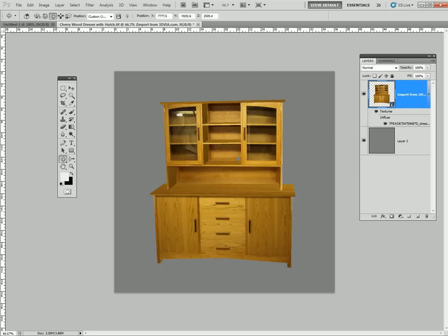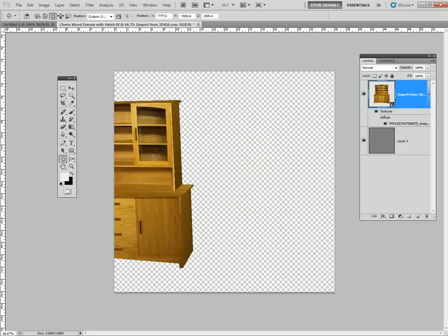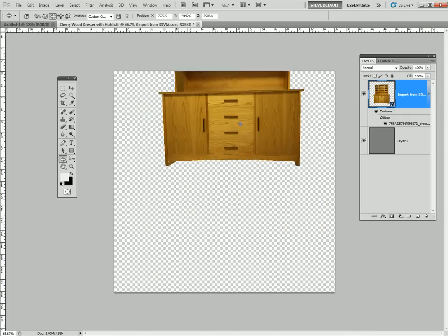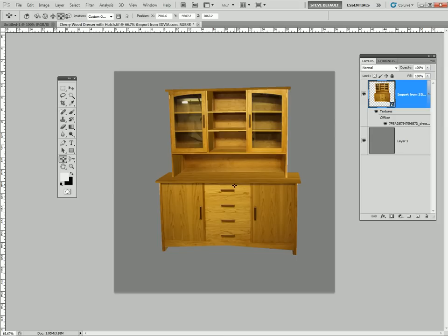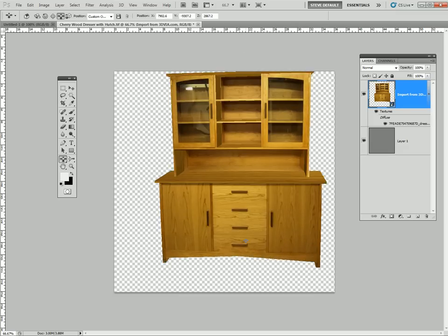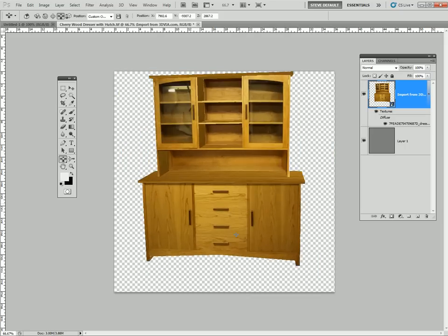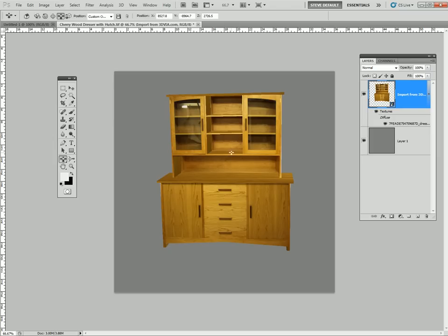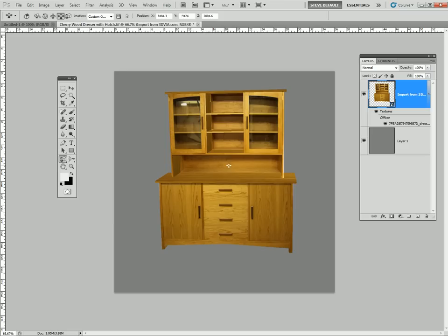Alright, so now we had the rotation, we did the roll. Let's go to the pan. The pan is basically panning our subject on either y-axis or the x-axis. So y, once again, is up and down, and x-axis is left to right. Let's hit the K key again, and now we have our Z depth. We're going in and out, moving the object in to the scene or back toward the camera or the viewer. And as you can see, Photoshop responds very well to how quickly it navigates the 3D object. Let's hit the K once again, and this allows me to resize my subject.